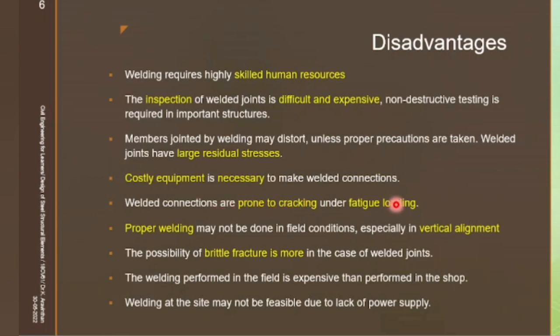What do you mean by fatigue loading? Take an example of a bridge. If one vehicle is moving on a bridge, you will have one jerk at the junction. Each and every vehicle going by gives a jerk at the junction. Steel material continuously experiencing that kind of jerk and force, the fatigue force is created. If load is there, the bridge will deflect. If the load passes, it will come back to its original position. Per day it can have around 10 to 20,000 cycles.